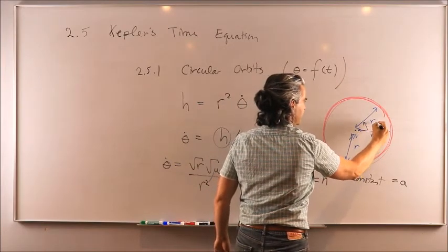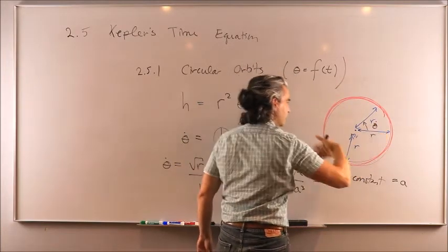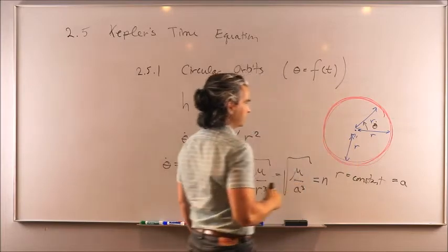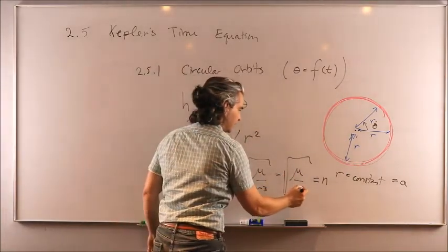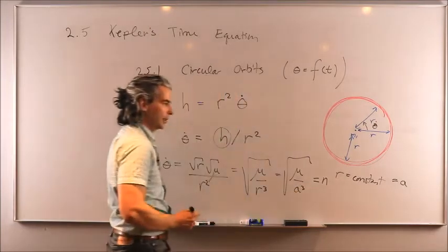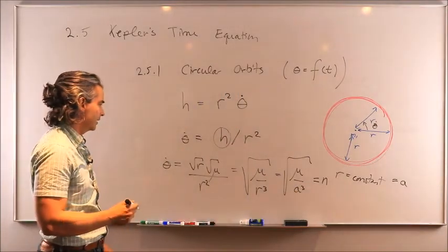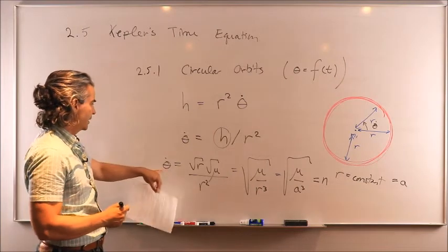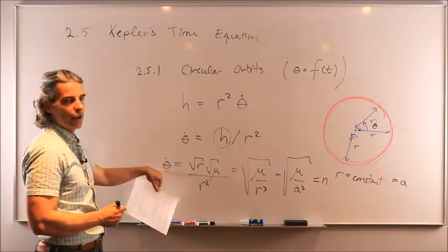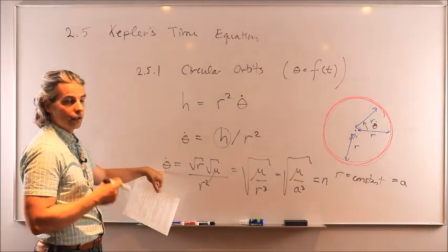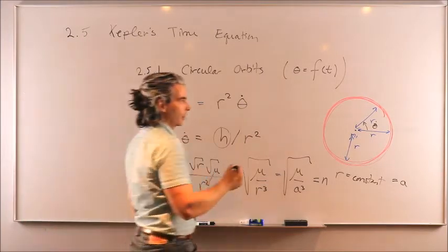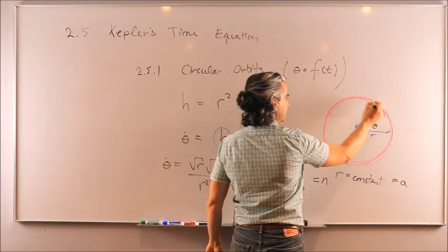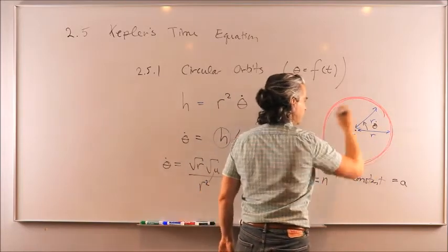So this is the speed at which theta evolves over one orbit. Now, this is a constant, and therefore the mean motion is also constant, as we've discussed in the past. So that makes sense, right? That for circular orbit, theta dot is a constant number in terms of radians per second. So in other words, the spacecraft does not accelerate or decelerate throughout the orbit.